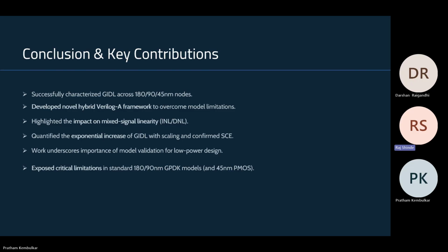Our analysis confirms that GIDL increases exponentially with scaling and strongly depends on both device geometry and bias conditions. Finally, we demonstrated that GIDL has a tangible impact on mixed signal circuit linearity, emphasizing the need for validated device models in low power designs.